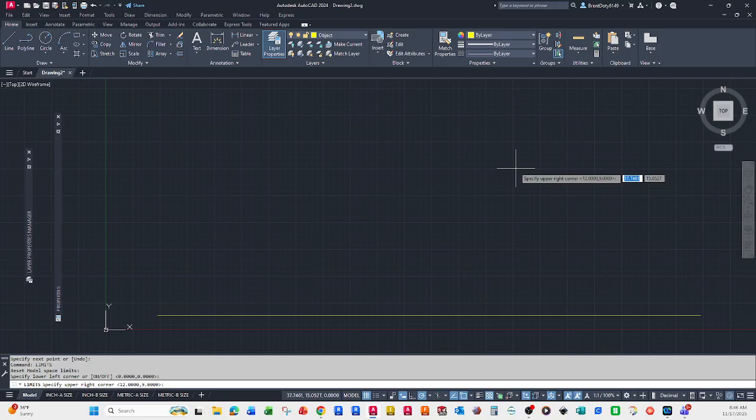And usually what I'll do is, so let's say it was 120 wide. Well, I'll just make it a square, because maybe I don't need that much height, but still, a square is easy, right? So I could type in 150, comma 150, enter. And now if I go back into limits, it should say 0, 0, and 150, 150, right? So that's good. And I'm just hitting enter to go through it. It's okay. All right, so now what you should always do next is a zoom, and then you're either going to do E for extents or A for all.